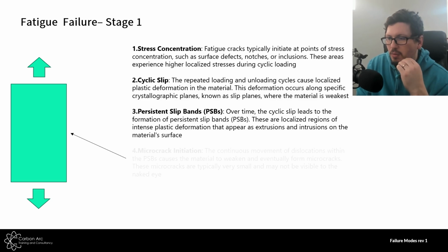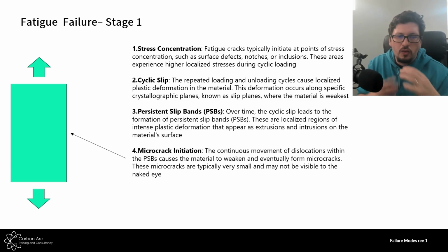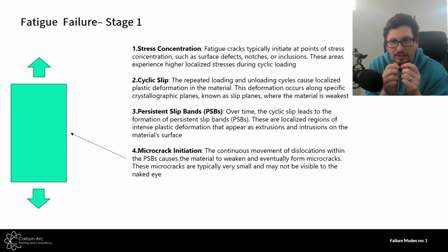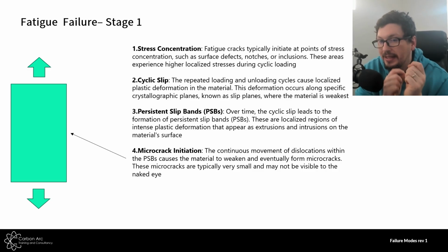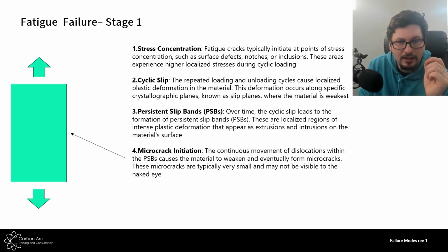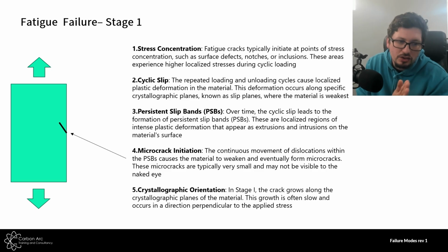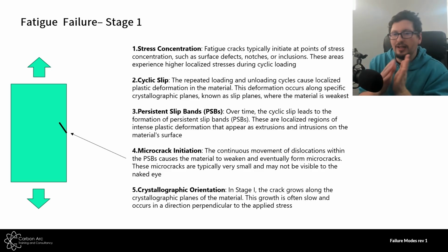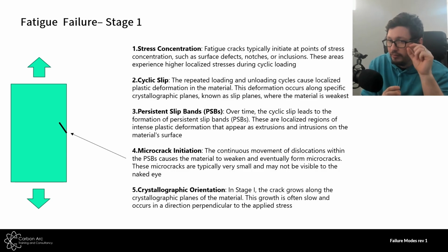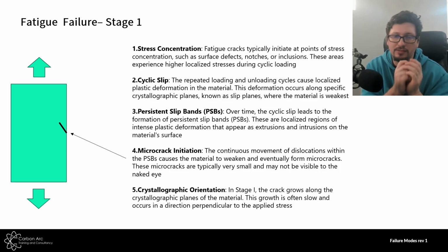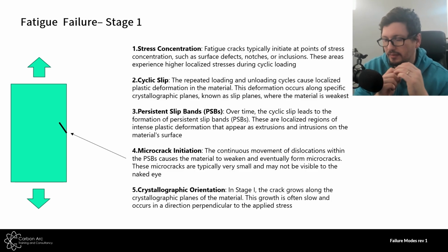What happens is that pressure on, pressure off starts to connect up at a micro level, and I start to produce micro cracks within my steel. From the surface of the steel, we get a crack that heads off at about 45 degrees to the surface of the material for a very small amount. So that's my initial micro crack.